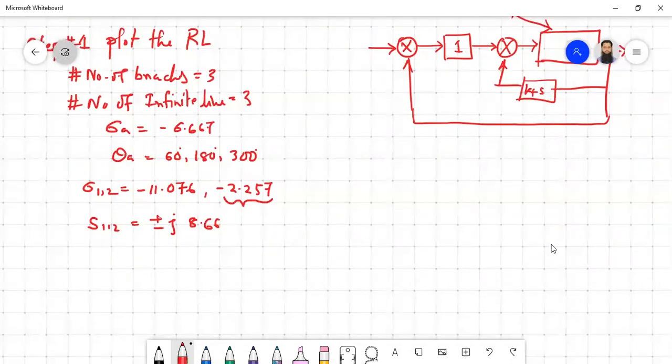Okay, so after doing all of this, then you have to know what the root locus should look like. Then also percentage overshoot is given. So for that percentage overshoot, you can find out the formula, and you're going to see minus ln of that formula. If you apply, then you're going to find out that zeta is 0.456. We already calculated this so many number of times.